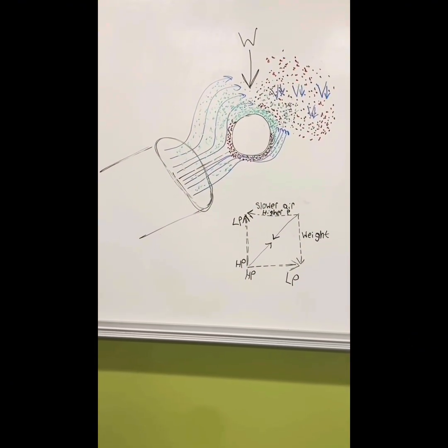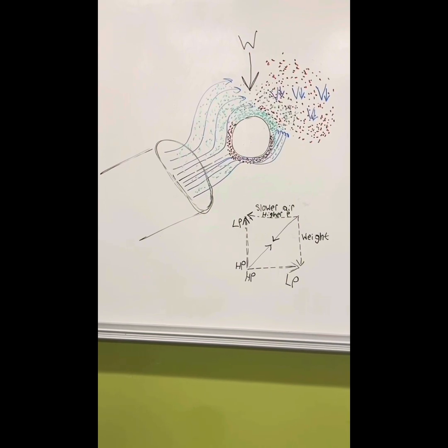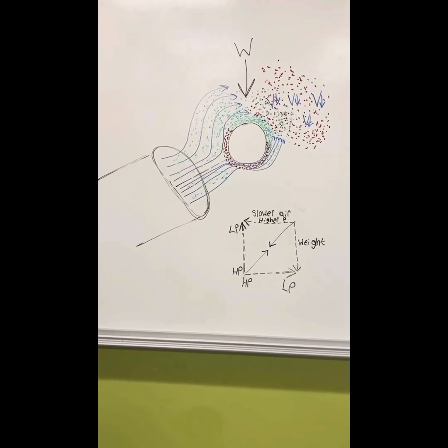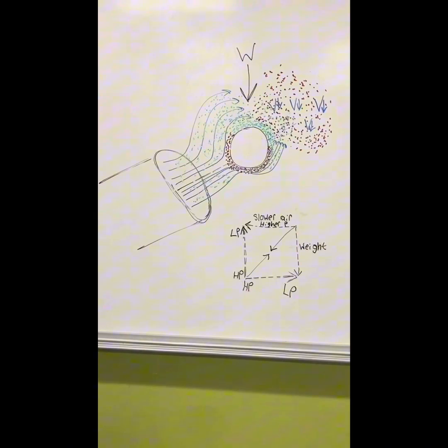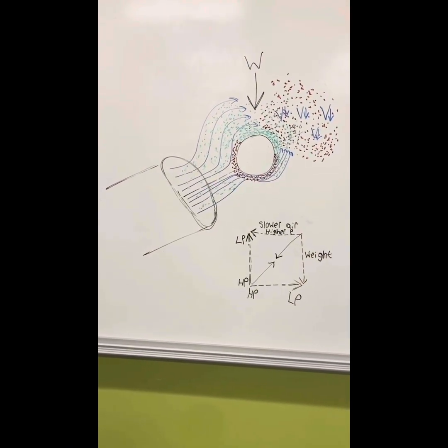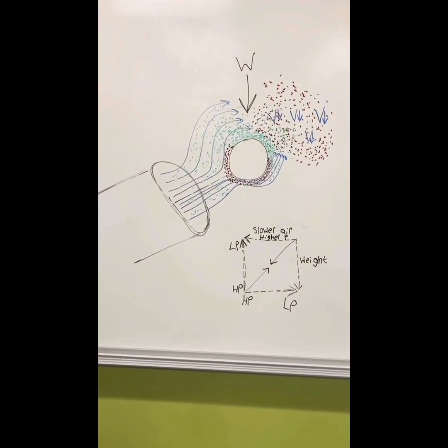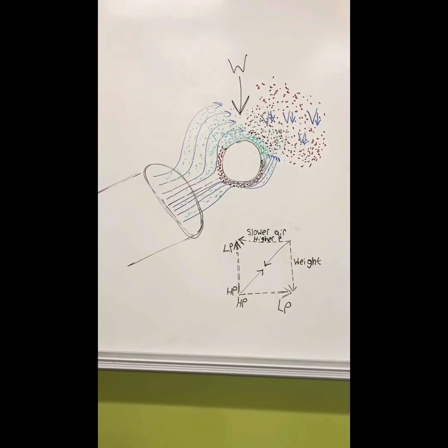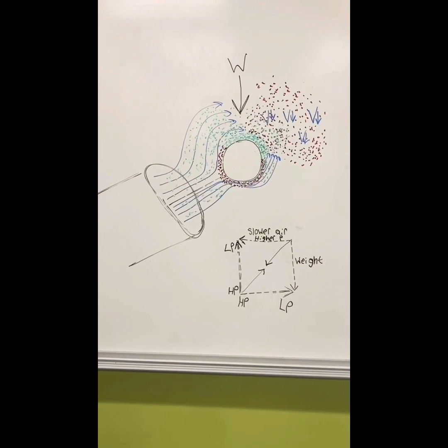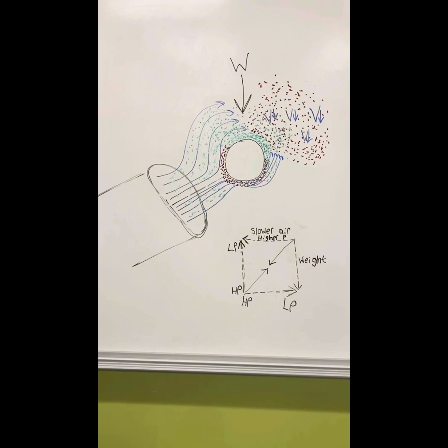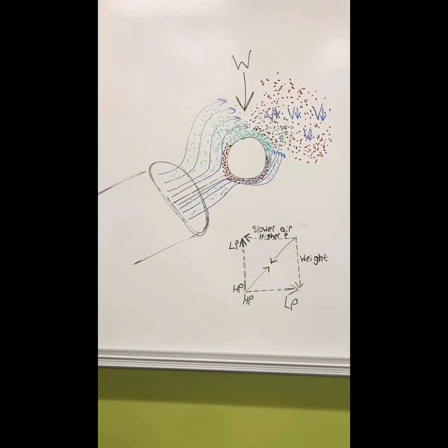The reason the ball is not horizontally ejected from the airstream is because the velocity of the air constantly decreases the further it travels from the nozzle, meaning pressure increases further from the nozzle. At the right point, the pressure difference caused by the horizontal component of the velocity is not enough to overcome the pressure of the slower moving air in front of it, balancing the forces on the ball.